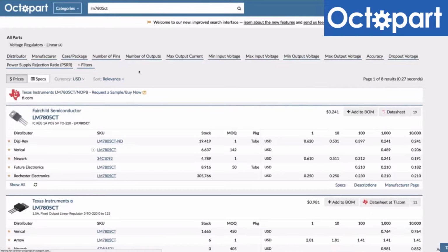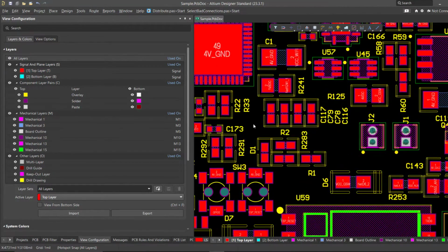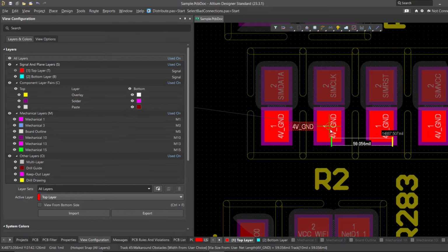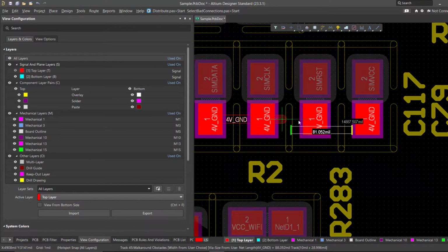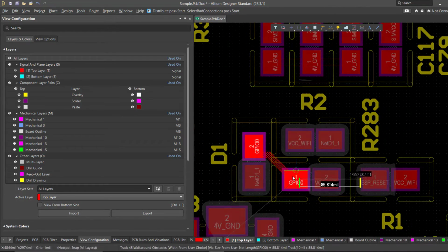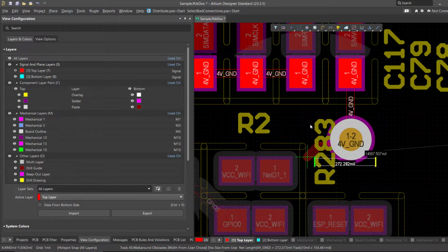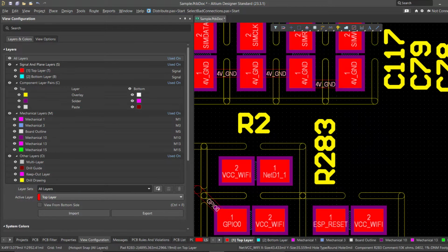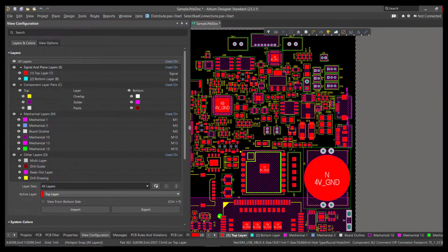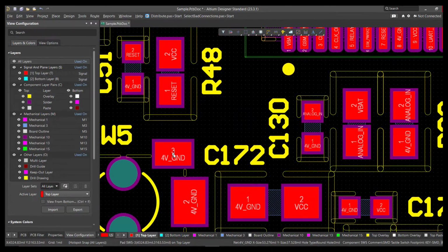Routing is the term used to describe the process of connecting two distant nets on a PCB. The process called routing connects various types of objects on a PCB. It can establish connections between pads, vias, or tracks. You can manually connect them, but now we will learn the faster way using interactive routing tools in Altium Designer. In this video, we will demonstrate how to connect objects on a PCB using interactive tools.